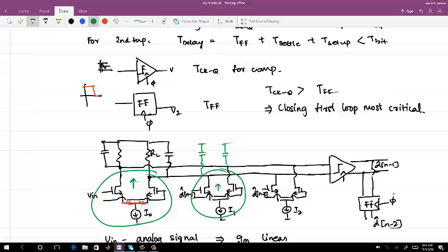No. So the thing is, if you increase I1 also to steer that current, think about it. This design is like when you design, let's say, for 100 microampere of current, your switch sizes will be minimum, or whatever minimum switch size is needed to steer that current while maintaining the voltage headroom. Now, if you want the same switch size to carry 2x the current, their overdrive will change. So think that each smaller value is optimized. You cannot decrease the size of that less than that.